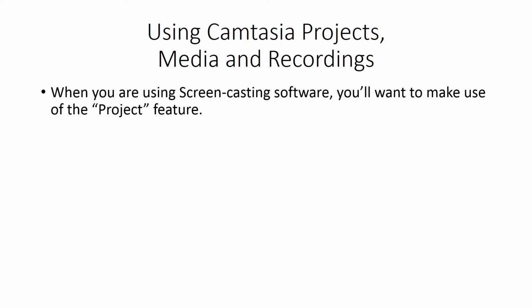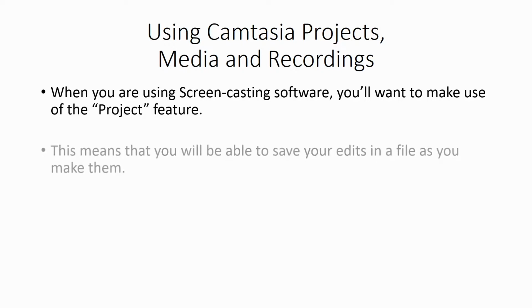Now in this video, we're going to be talking about Camtasia projects, media, and recordings briefly. We talked about in the main course that you want to make use of Camtasia projects. So yes, you're going to record video. Yes, you're going to have a file that you're going to be working with. However, you want to be in the habit of also using the project files, which is any changes that you make, anything that you edit, anything that you add, any annotation that you make. When you save it over in that project, what happens is you haven't done anything to the original recording, and it gives you the opportunity to work with that original file over and over again in different ways.